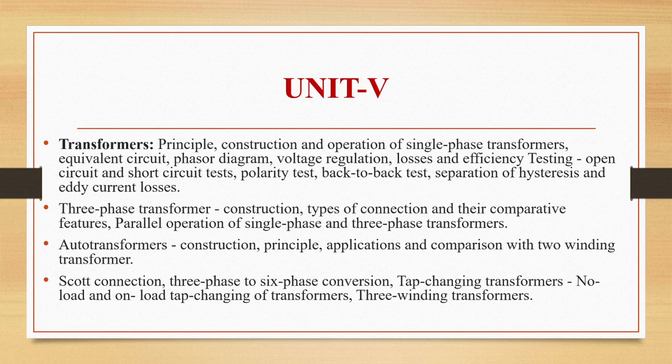Based on single phase and three phase, they are classified as single phase and three phase transformers. When you see the operating principle, it is the same for both these transformers, that is mutual induction. Transformer works on the principle of mutual induction. Basically there are primary and secondary windings. Two windings will be there in the transformer and they are wound on a common core. The core will be laminated and it is made up of silicon steel material.